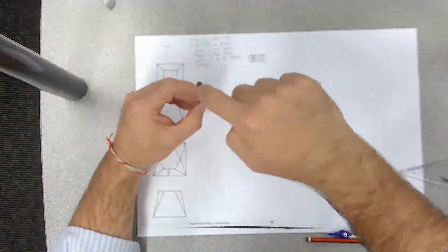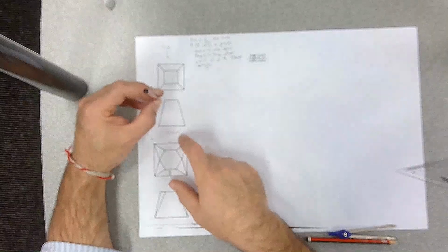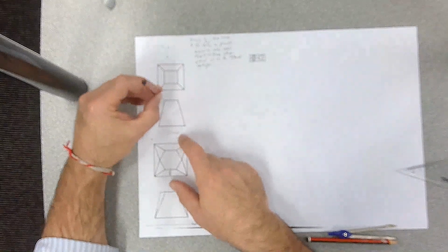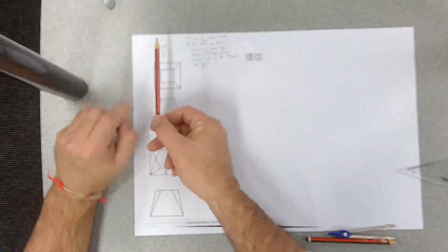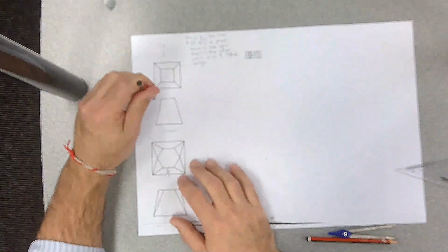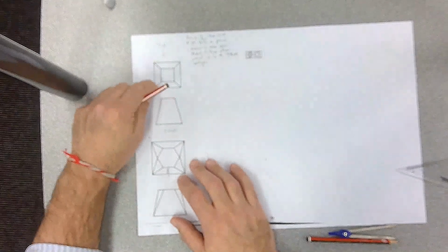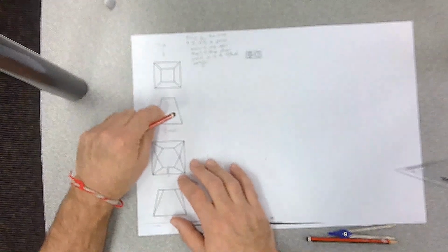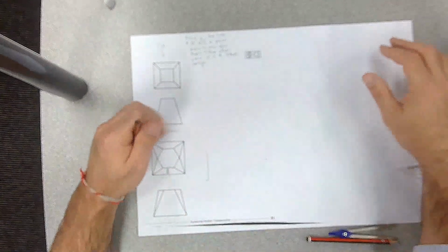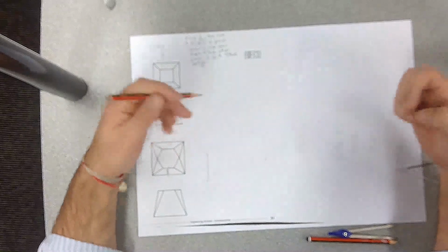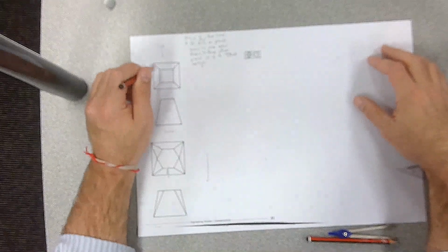Okay, now that's a long sentence, but all that means is basically if you're looking at the end of the line and you just see a little dot, say in this view here, then obviously when you look at it and that line becomes this line here in a top view, the point views are always going to become true length in the other view. So if you had a point view in this diagram, it will be a true length here. If you have a point view here, it'll be a true length in this diagram. Okay, that's the first rule you've got to remember, the point view rule. Point view of a line in one view is going to be a true length of the line in the other view.